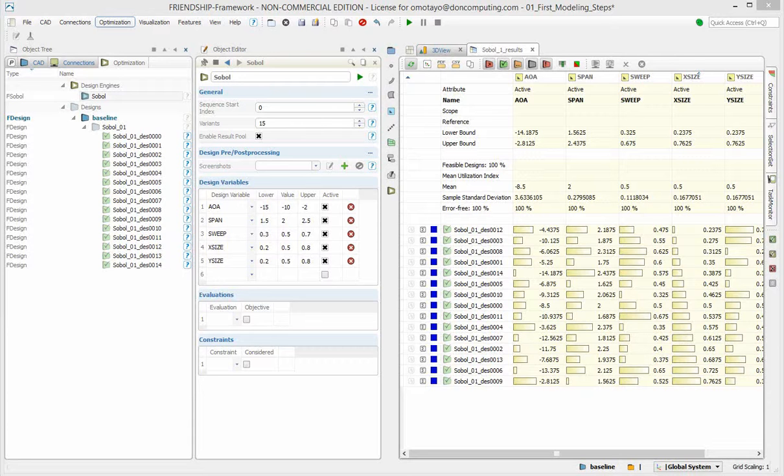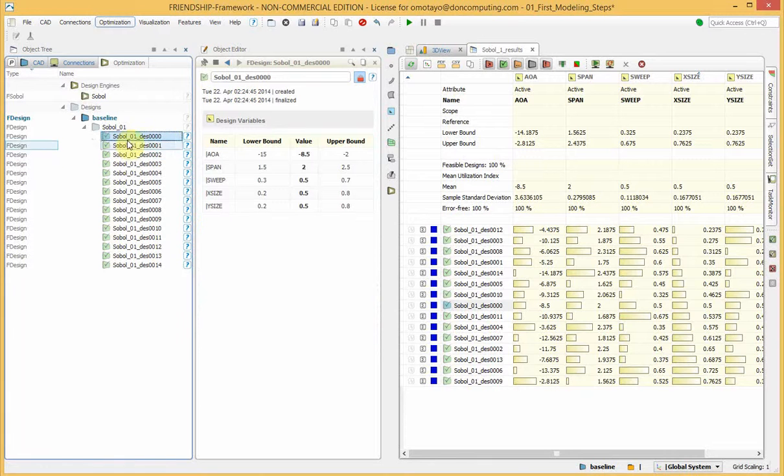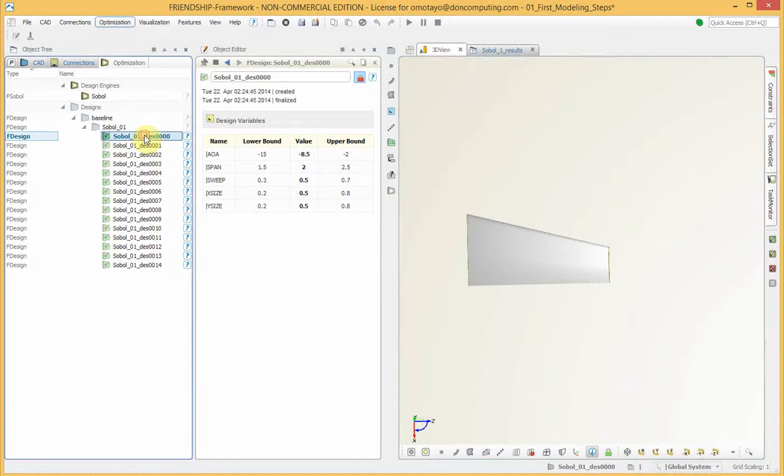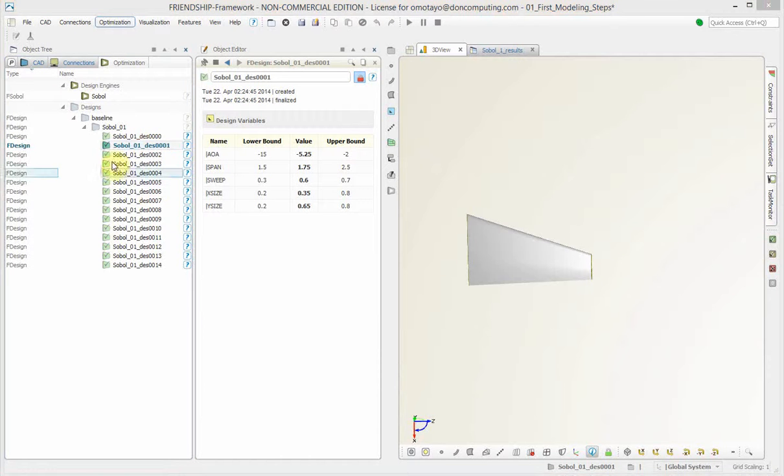If you browse through variants, by double-clicking on a design, note that they are in a read-only mode by default for protection purposes. If you want to edit, modify or continue design work on such variants, the lock needs to be deactivated. In the design tree, double-click on a variant so that it will be the current design. Click on the red locker icon in order to remove the lock. The icon turns green, which indicates that the variant can be edited.